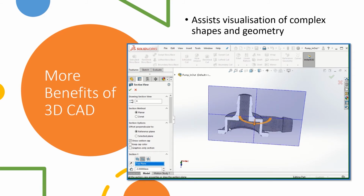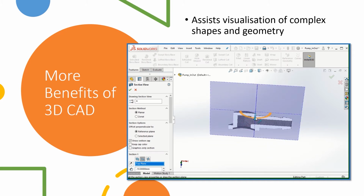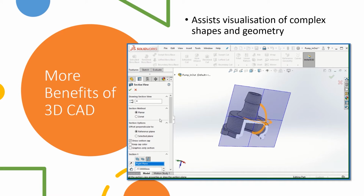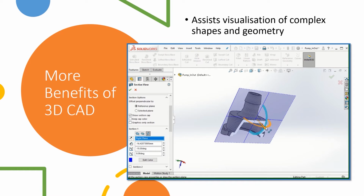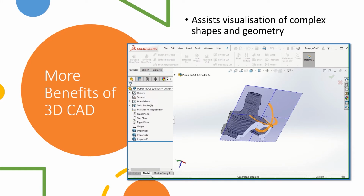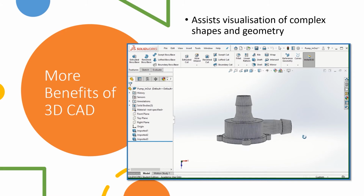I can be checking the wall thicknesses on all of these to make sure the part's going to be strong enough, make sure there's no gaps. I can again switch it around into all these different views. I can actually do this on angular views as well. If I cut that down to angles, you can see I can cut up through this, but I can look at this part in any way I desire through a sectional view. Just going to turn the sectional view off.